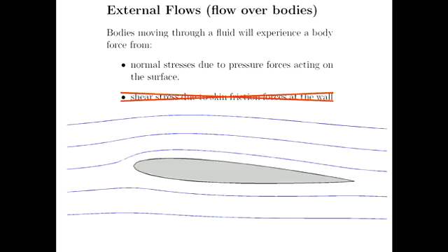And for certain flows that we look at, that's not really a problem. So, for example, on an aerofoil, the vast majority of the forces are coming from those normal stresses due to those pressure forces. The shear stresses are very small. They make almost no contribution to the lift, and really a tiny contribution to the drag coefficient on that aerofoil.